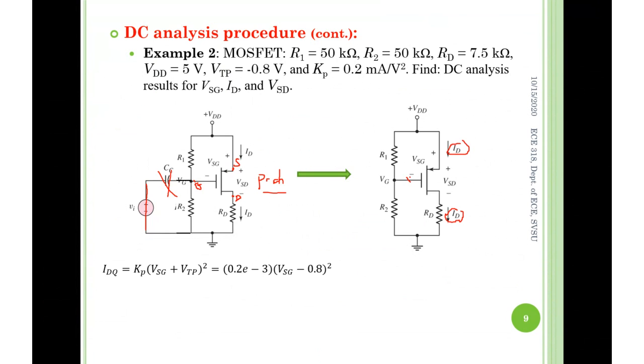So here is an open circuit, very nice. And then we start to think about the VSG loop KVL. It's VSG, not VGS, because it's a P channel. Where is this loop? Up here, does it make sense? You need the loop containing VSG. It's not about trying to memorize the location. It's the loop containing VSG, not the loop down here.